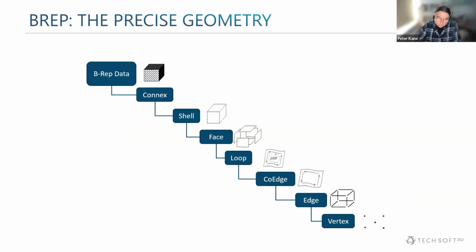Just a little more on when I talk about BREP data and exact data, the topological structure of that data is shown here. And without going into too much detail, I think the important parts of that structure that are relevant today are the fact that a solid might be divided into individual faces. In this case, it's a cube with 6 faces here, but in practice, for more complex objects, you're going to get faces made out of different geometries, cylinders, NURB surfaces, and so forth.